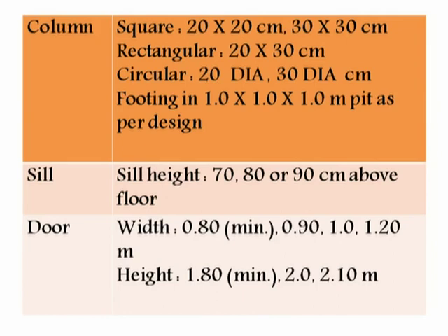The dimensions of the doors are: the width of the door is kept a minimum of 0.7 to 0.8 meter. Then it is 0.9, 1 meter and 1.2 meter. For public buildings, the width is kept normally 1.2 meter. The width of the external door will be around 1 to 1.2 meter, and internal doors will have a width of around 0.9 meter.